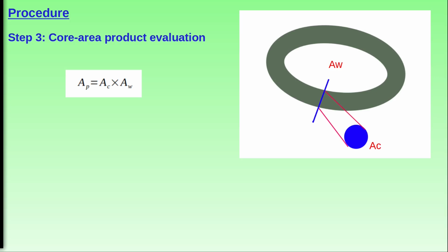For the magnetic core, the max flux depends on the sectional area of the core and on the material of which it is made. The window area comes into play when you consider the length of the path the flux has to go through, like in the case of the length of the wire a current has to go through. It also comes into play when considering the space the wire will occupy when wound around the core. These entities are correlated through the following equation.